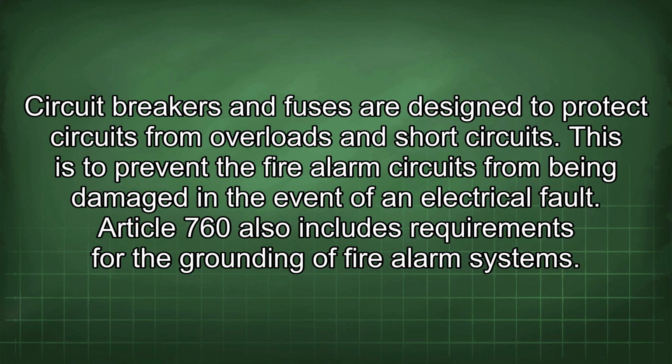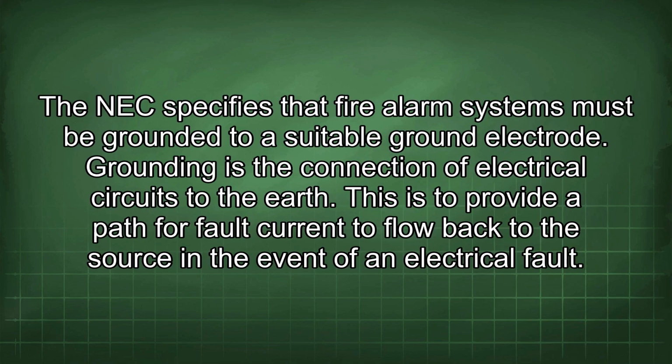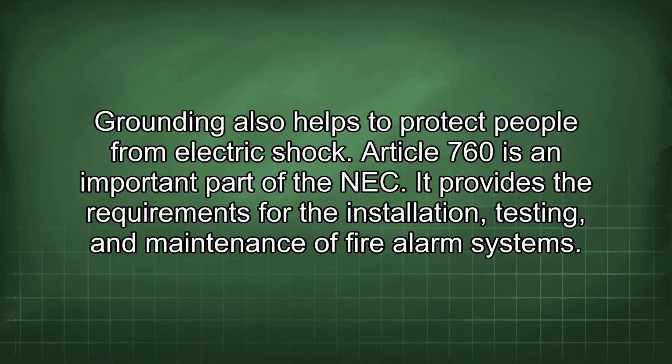Article 760 also includes requirements for the grounding of fire alarm systems. The NEC specifies that fire alarm systems must be grounded to a suitable ground electrode. Grounding is the connection of electrical circuits to the earth. This is to provide a path for fault current to flow back to the source in the event of an electrical fault. Grounding also helps to protect people from electric shock.